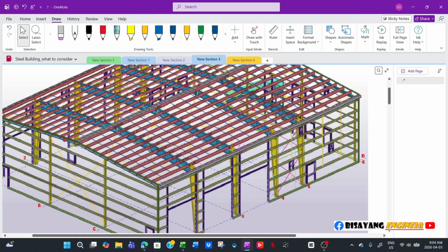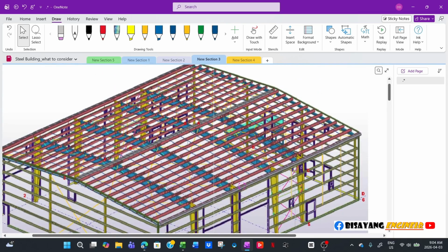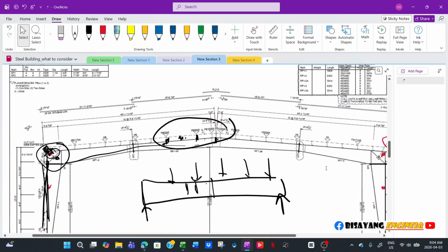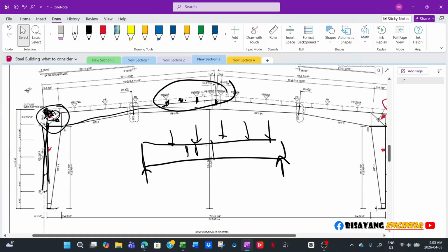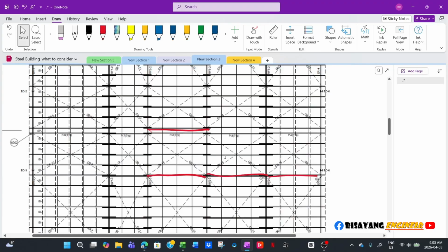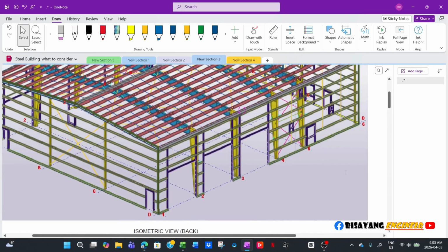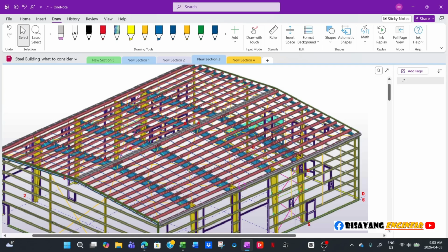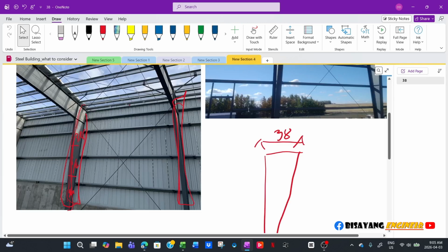That's a really small section compared to what I got when I do a mock calculation. Even this building here, I think in my calculation I got W27 by 100 or something. And this is only like 22, 23 feet, so that's only 22 feet. That's basically half of what he has, you know? So I told him, that's nothing. Just proceed with your calculation and select bigger sections.